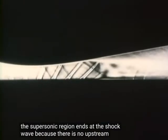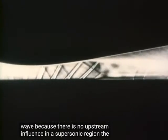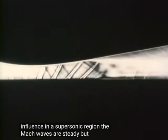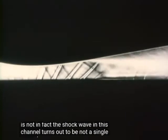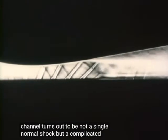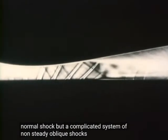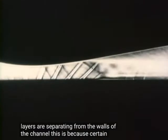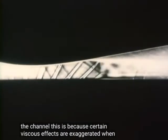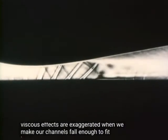Because there is no upstream influence in a supersonic region, the Mach waves are steady. But the shock wave is not. In fact, the shock wave in this channel turns out to be not a single normal shock, but a complicated system of non-steady oblique shocks. The boundary layers are separating from the walls of the channel. This is because certain viscous effects are exaggerated when we make our channel small enough to fit into our Schlieren beam.